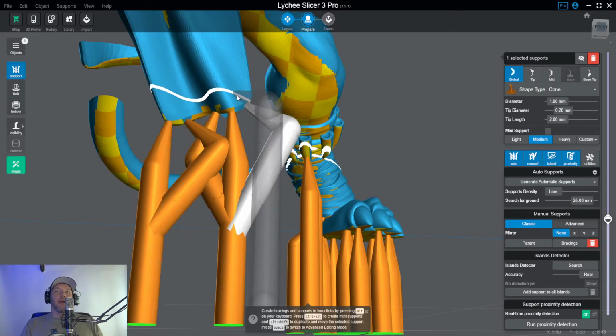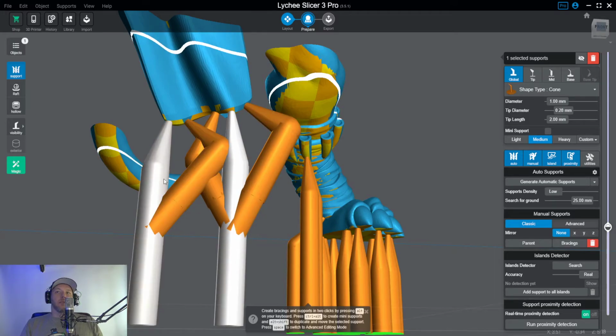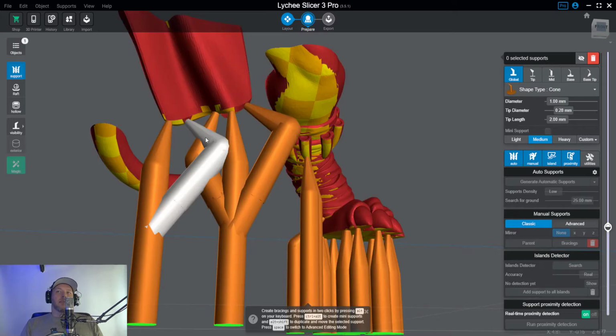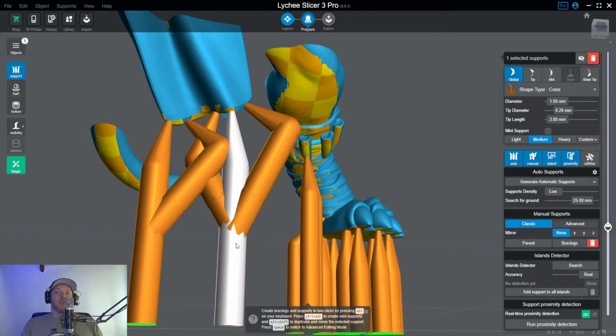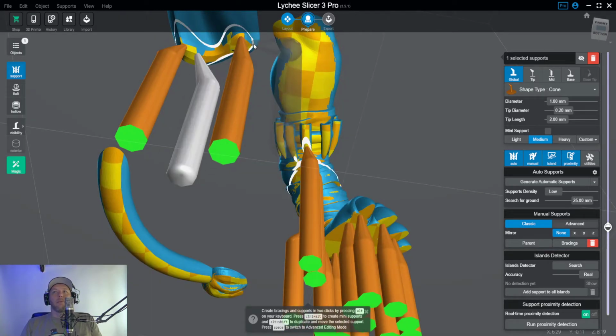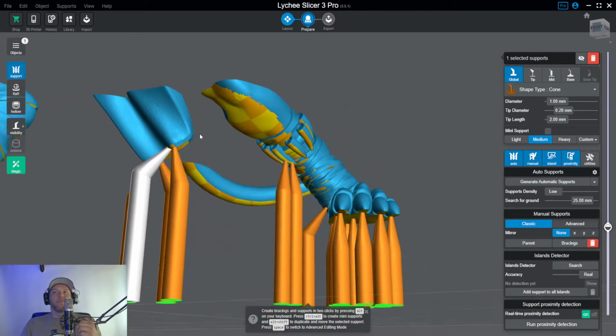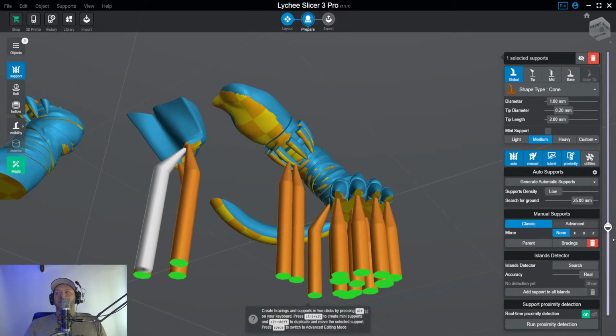We just have to keep in mind that once this starts pulling, it's going to be pulling on the pillars, on the trees. Even if it starts pulling on these branches that we've created, those branches go back down to the trees. It's going to start pulling on those trees again. So we need to be confident that these tree trunks are going to be strong enough to withstand all of the forces being pulled. If you determine you don't think so, drop a regular support. Make 2 new trees. That's totally okay. They're happy little trees, you guys.